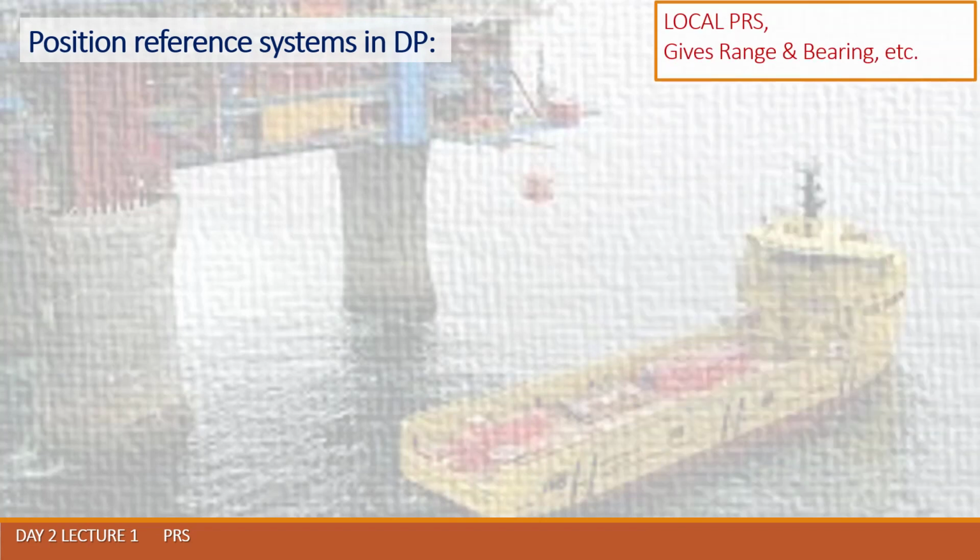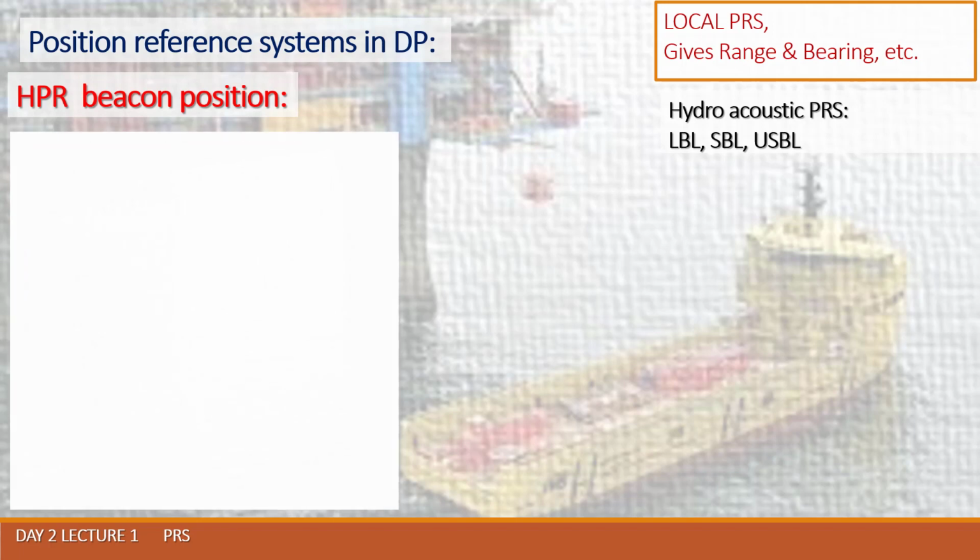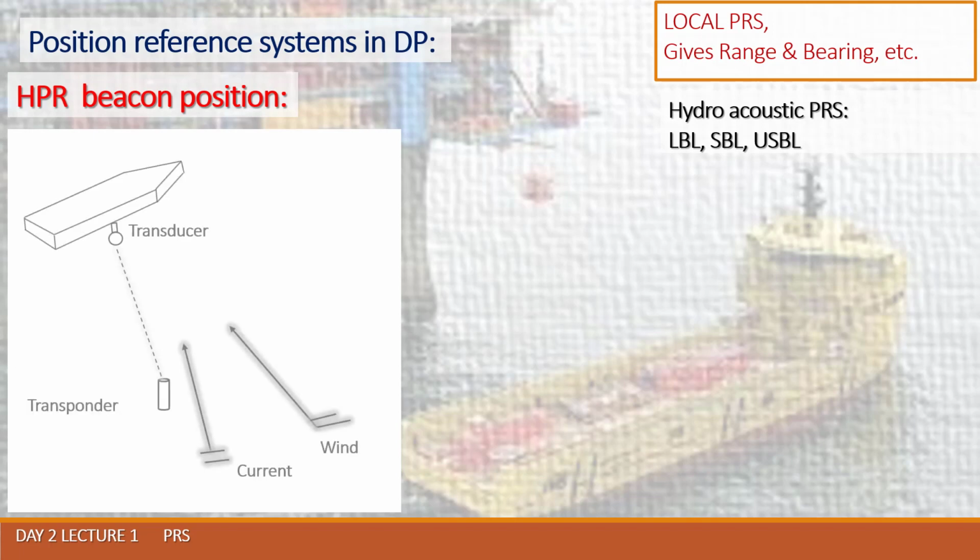When the SIP beacon is installed at the bottom, we need to keep in mind some precautions. The HPR transducer may suffer from the noise produced by open vessel thrusters and main propulsion. And please remember or mark somewhere: low thruster RPM makes more noise for the HPR system compared with higher RPM.